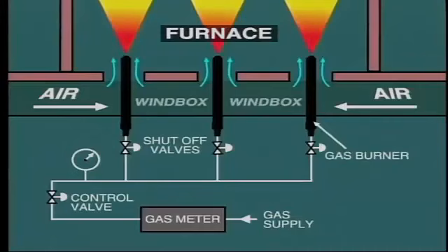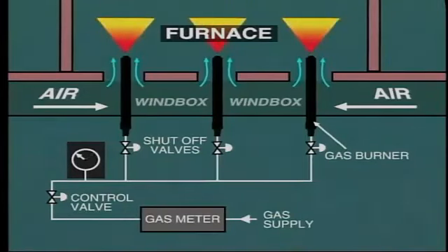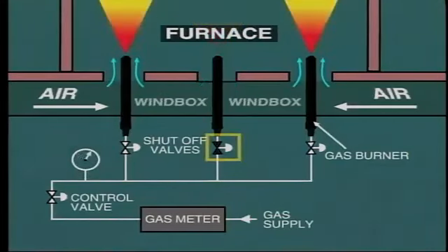Control of heat input to the natural gas boiler is similar to oil firing. That is, the flow of fuel to the burners can be adjusted by control of the fuel supply valve, at least over a certain pressure range. However, if the fuel supply is allowed to fall too low, we may get unstable combustion. In this situation, it's necessary to shut down one or more burners completely, and so raise the supply pressure to the remaining in-service burners. Now, we do have more to say about controlling combustion, handling the ash,